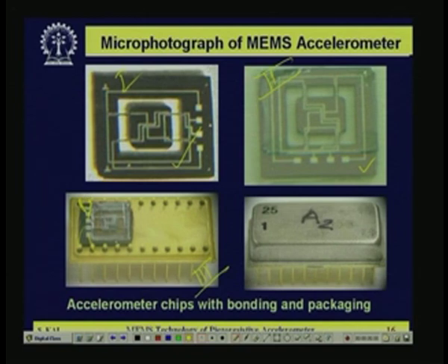The 4 bonding pads, after this is the encapsulated case, and on the case is a metal can basically. First thing is the whole chip, which is shown here, silicon glass, is to be fixed at the middle, and then wire bonding is done, then the top cap layer. If you put the top, this is not the sensor cap layer, but it is the encapsulation. The top metal can encapsulation is covered.